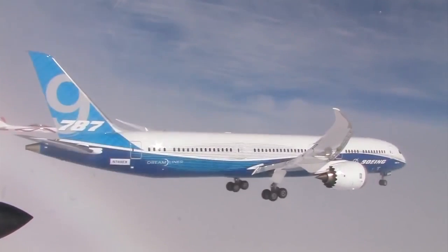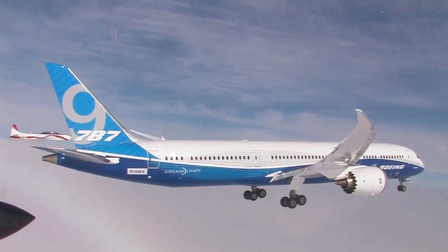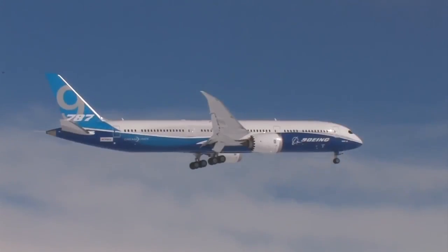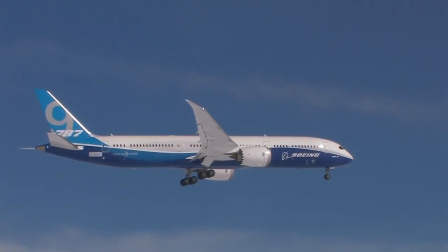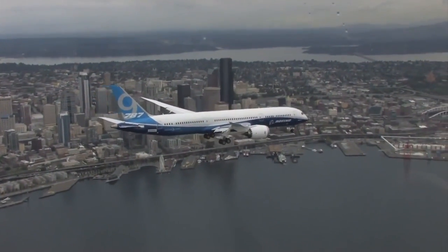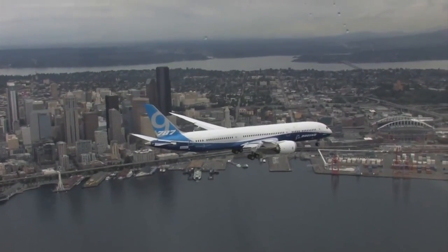In order to simplify the pitch motion of an aircraft, we will make a few assumptions. First, the aircraft is at steady level flight at constant altitude and constant velocity, therefore balancing the thrust, drag, weight, and lift forces in the x and y directions. Second, we will also assume that the change in the pitch angle will not change the speed of the aircraft.